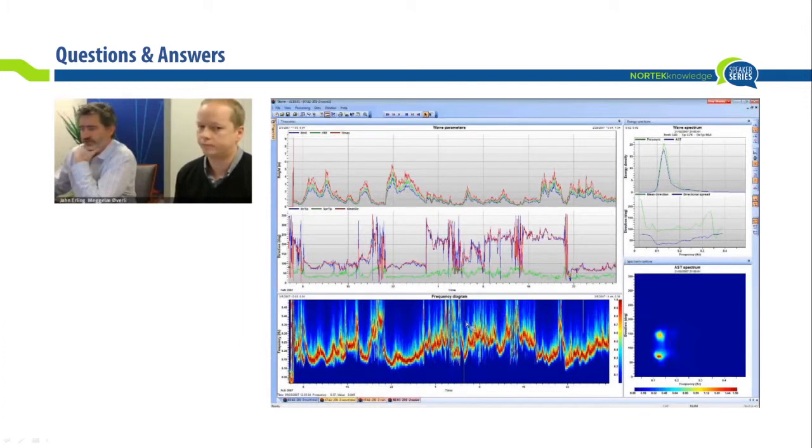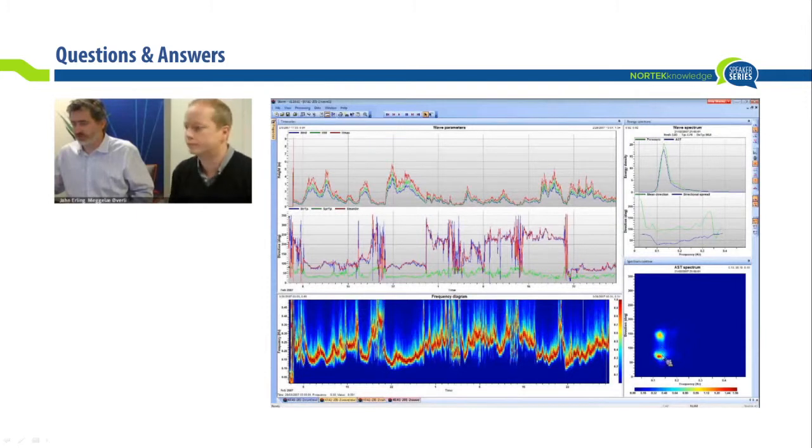particular plot down to the right, this is the full directional distribution. What's interesting is that you see two energy peaks at the same frequency, but coming from two different directions with two different intensities, which is indicated by the color. Typically, when I see this, it's an indication that the AWAC was close to a reflecting boundary. That could be close to the shoreline that's reflecting, or a seawall or whatnot. So you have a lot of symmetry in the directional spectrum here. If I step forward, we should see this in several of the wave bursts. So that's usually an indication of that happening.